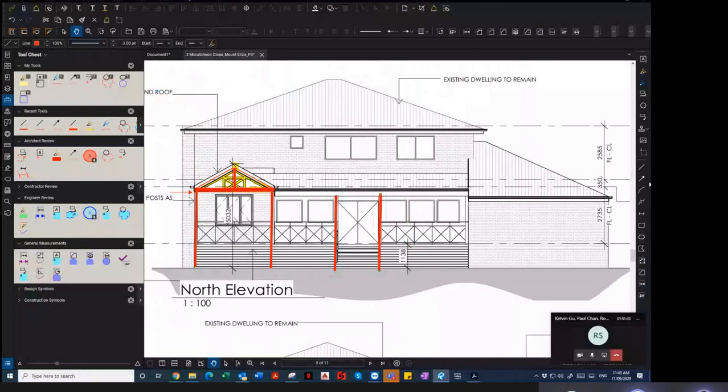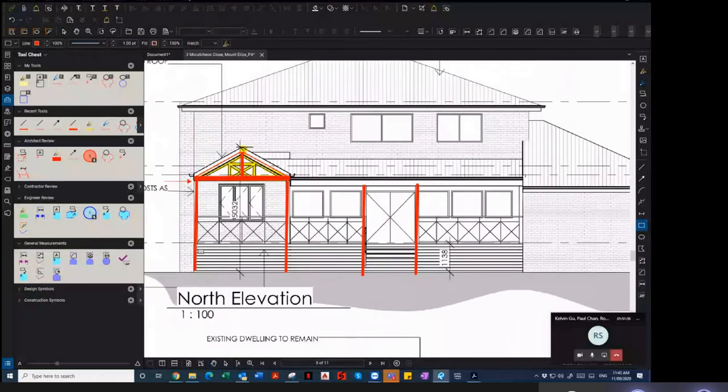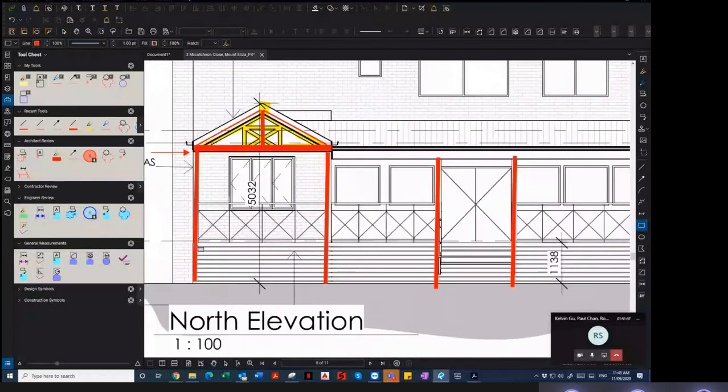And what you could have is your bearer, which is sitting at this level over here. And you could also have something over here where you could brace your floor system. And this is critical, because what happens is that then your post is actually cantilevering from here. You know what I'm saying? Once you brace it to this point.